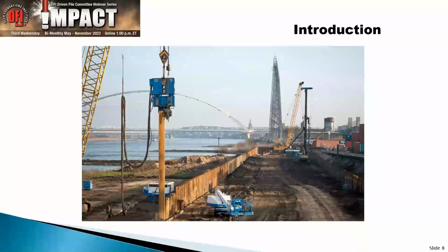We also have plenty of sheet piles. And with sheet piles, it is almost a no-brainer. We drive those with an impact hammer or with a vibratory hammer. So the question then is, well, if we can do this and feel comfortable to do this with a sheet pile, why not with any other type of pile?